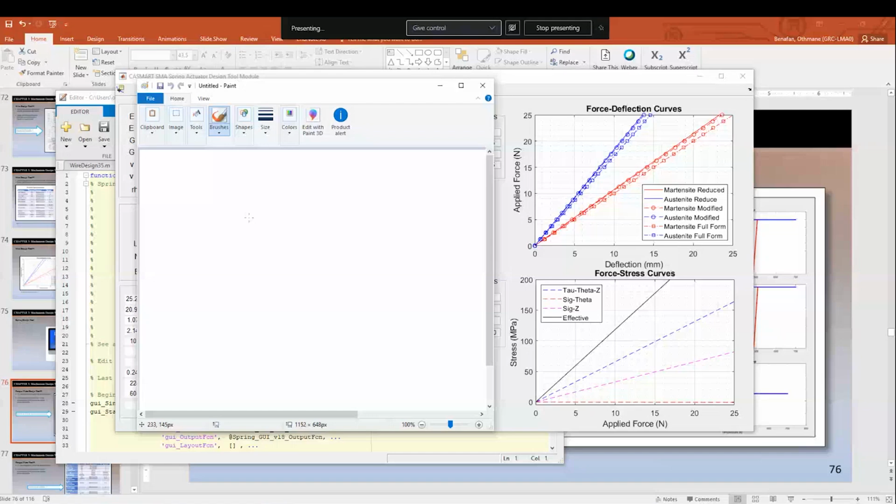So now this basic form here takes multiple variations. This is the simplest form, but if you want to account for some geometry correction, you have to multiply by a factor known as Wahl's factor. If you need to account for large helix angles, imagine you stretch this spring very, very far. Well, that's what we call the full form, after Ancker and Goodier back in the 1920s. They use a much more modified factor that accounts for the helix angle, basically. So this is the function that it's solving here.